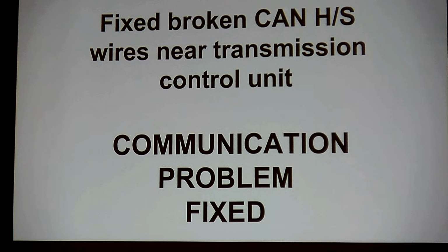You know how when you pull on wires, sometimes they're so tight you can't even get them out to put an amp clamp on, and sometimes you get a yard out of it? When they're tight and it takes the hit and it jerks the wire, they just break, clean breaks right at the turns. Don't cut the whole wiring harness open. Just go up to the first or second turn. They're always broken there for me. It's where I expect to see them when they've been hit. And the shop didn't get it because he just fixed what he could see down where the actual damage occurred. He's not thinking about those wires being broken up on top.